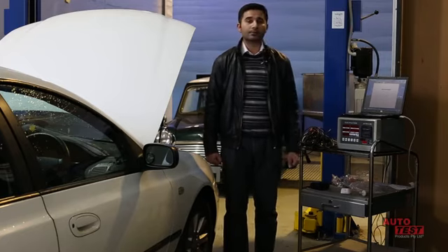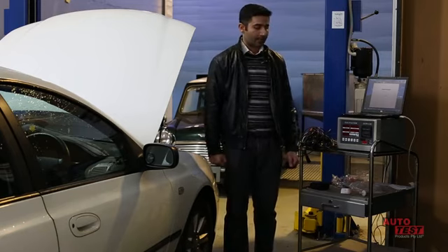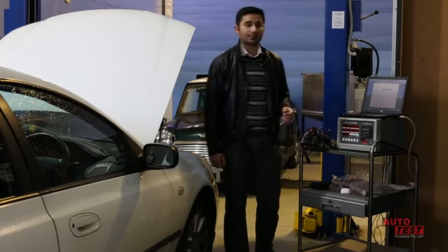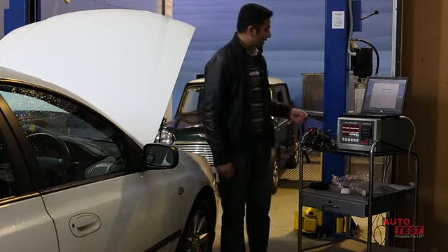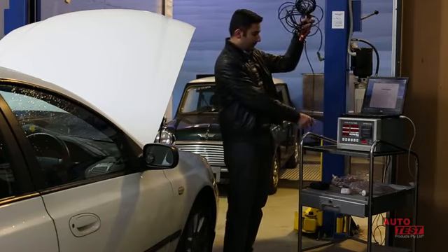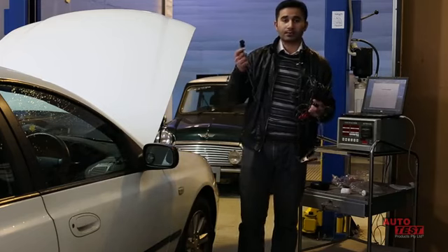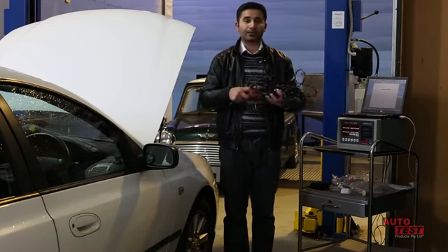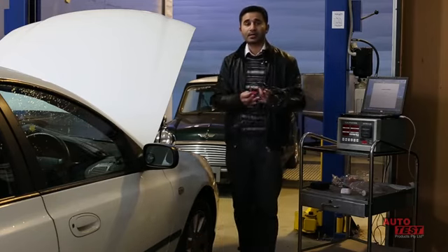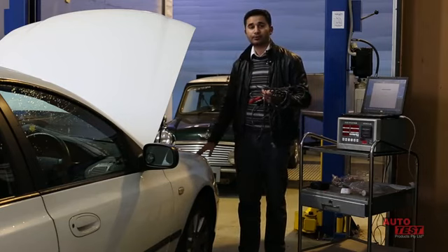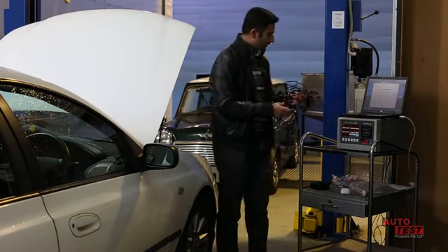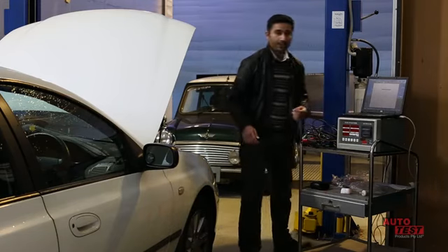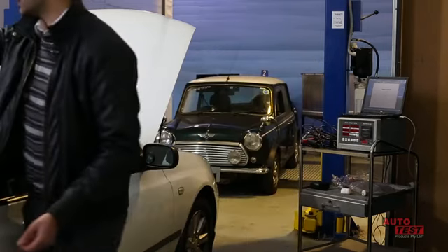Okay, we're now going to turn on the smoke meter and gas analyzer, and for that we need to provide power cables to them. For the smoke meter, I'm going to use DC battery cables. Here is a cable. It's got one connector that will connect to the smoke meter, and these other clamps are battery clamps, and I'll connect them to the battery terminals of this car that we're going to test. For the gas analyzer, I'm going to use an AC source, and I have just connected the AC cable to it, which I'll show here.